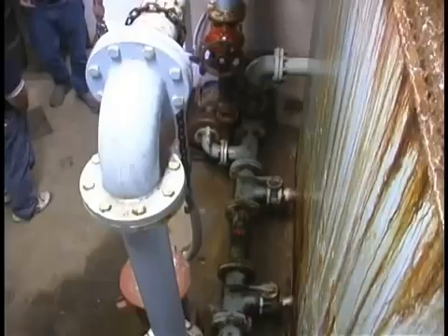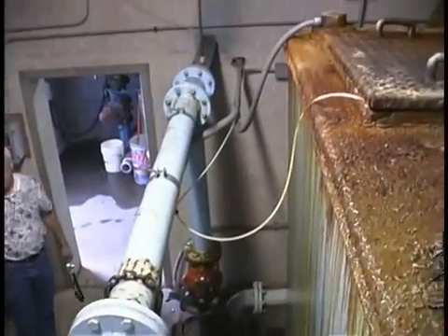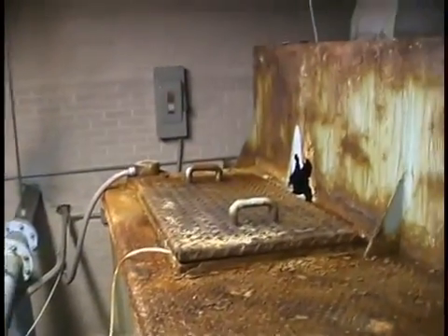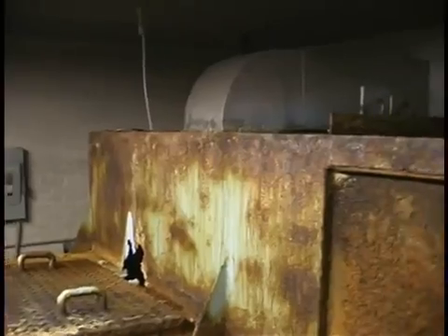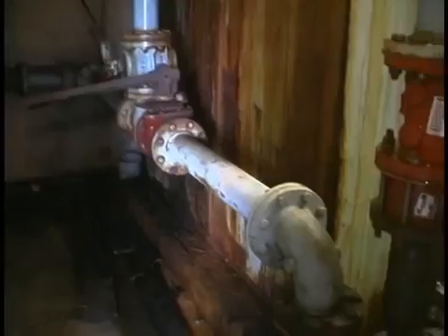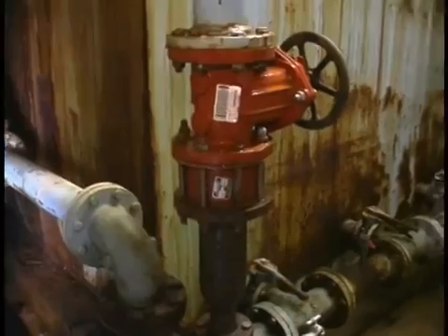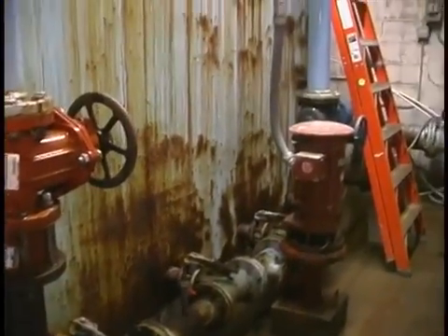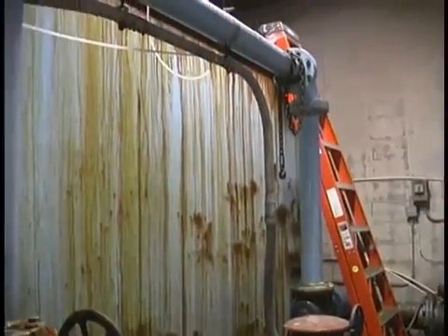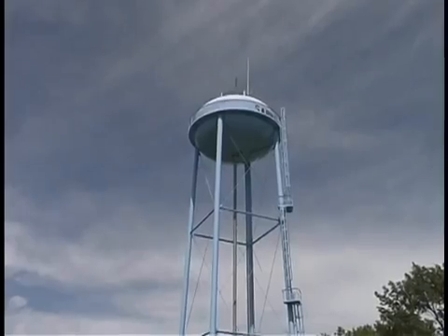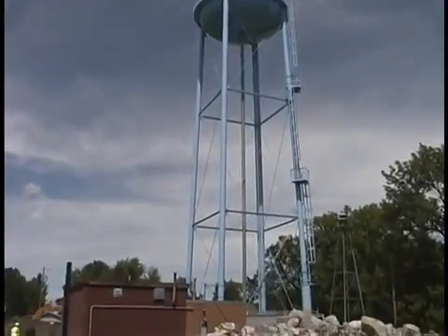The present plant has deteriorated to the point that the raw water arsenic concentration is 45 micrograms per liter, and the treated arsenic concentration is about 40 micrograms per liter. The community is combining the EPA demonstration project with other funds to complete a $1.1 million expansion project. The new treatment facility will be constructed on the existing site.